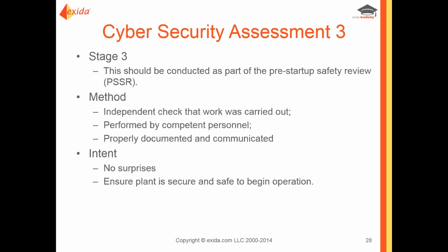At the end, you'll do a cybersecurity assessment 3 at the end of design and implement. This should be conducted as part of the pre-startup safety review. You can treat it separately, but I personally believe that the Cybersecurity Assessment 3 is simply a contribution to the PSSR. As before, with all of these cybersecurity assessments, the work should be checked.